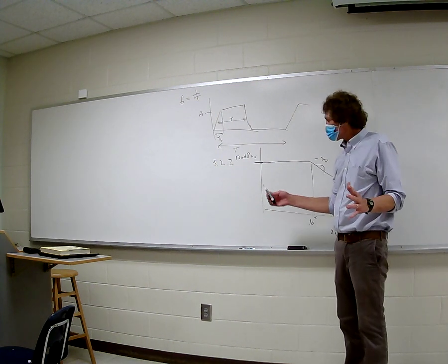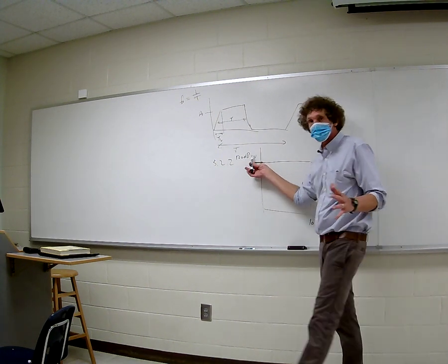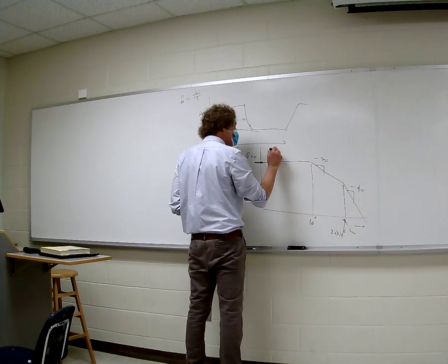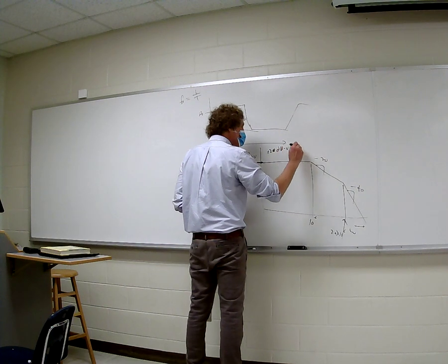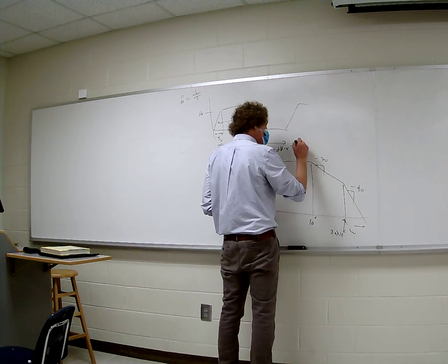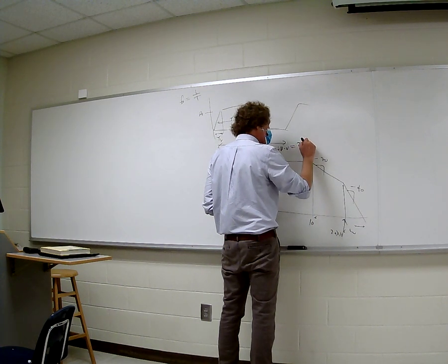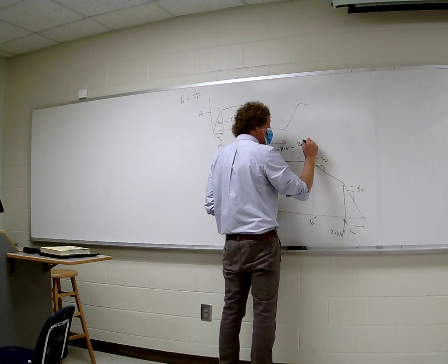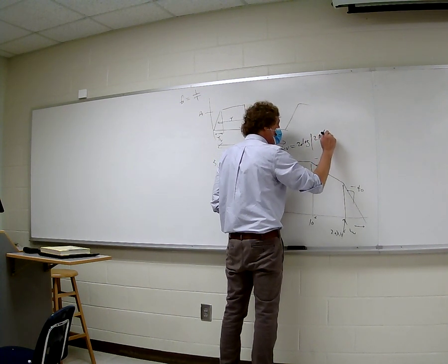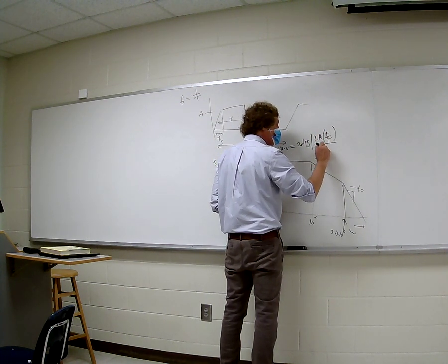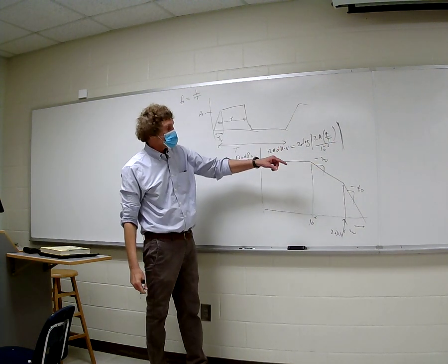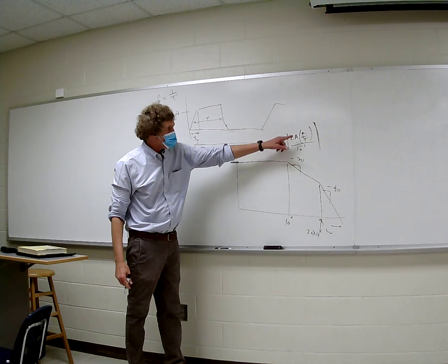And look, this right here, 120 dB microvolts, is equal to 20 times the log of the magnitude of 2A times tau over T, that's the duty cycle, over 10 to the minus 6. So if I asked you for A, if you knew the duty cycle, typically 50%, 0.5.